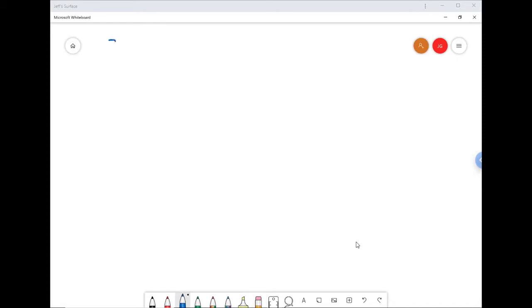Okay, so this first wire is made of copper. Cu is the abbreviation for copper on the periodic table. It was 10 meters long, and 22 was its wire gauge. AWG is American wire gauge. If I know that, I can look up in a table what its diameter is. I supply that for you in the lab write-up this week.